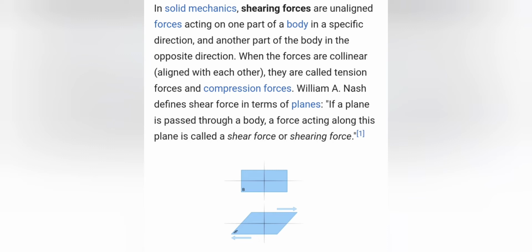Now let's see where shear forces are generated in civil structures. Let's assume a construction site which has soft soil for the foundation. For this site, pile foundation is used for the building. Assume a single pile for representation purposes only. The load from the structure will be passed to the ground via friction piles. Friction or shear forces between soil and pile foundations keep the building standing still, and if the length of the pile is not sufficient to resist the building forces, then the foundation will fail.